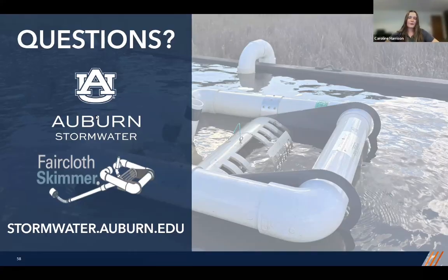Yeah, definitely. So my first phase of testing was the sediment basin skimmers, so I was very used to that. And when time came to test the post-construction skimmers, it was very interesting to see the change in how those skimmers performed compared to the sediment basin skimmers.